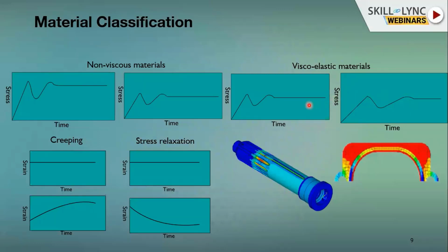It also remains constant over a period of time, the stress, and it keeps varying depending on the characteristics of each viscoelastic. So creeping is a phenomenon which we spoke about. Although the stress is going to be constant over a period of time, definitely your strain is not going to be constant. It keeps increasing further over a period of time. That's why we call it a long process. It especially happens at elevated temperatures, also if there is any change in room temperature where you had kept that specimen.